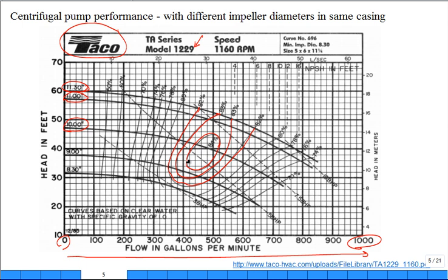Now they put them even outside the region that you would want to operate this pump. Down here, you don't really want to be operating down there, nor in here. But they don't even extend these all the way down, do they? You don't want to be operating way down there. This is where you want to operate, okay? Even a subset of this is shown on this plot. So they put a lot of information on these plots.